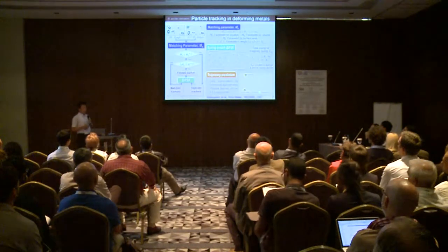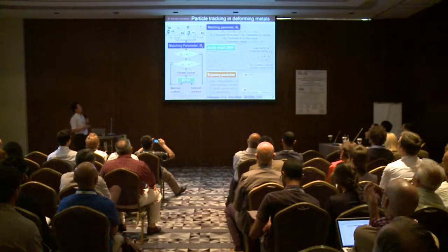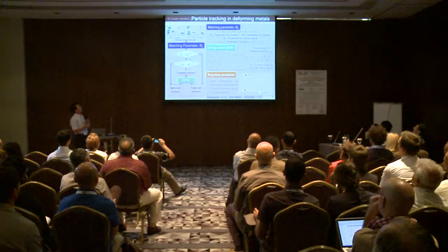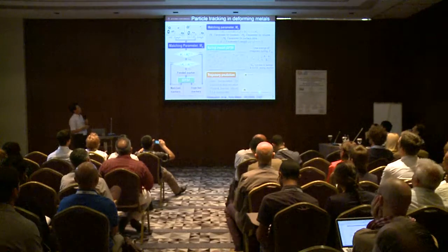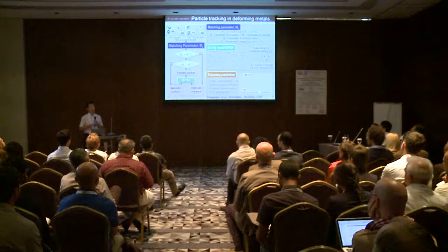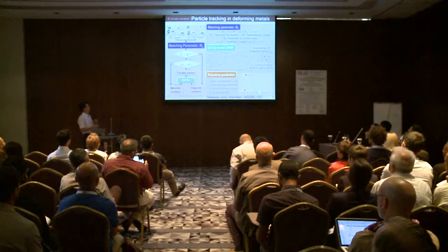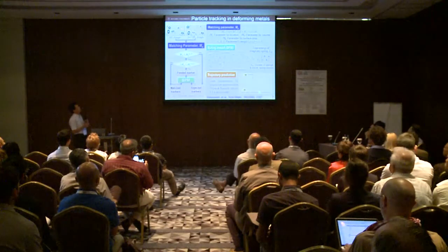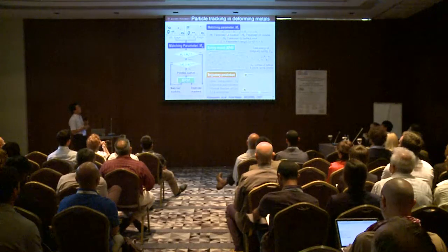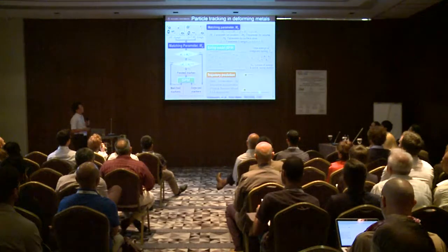So we would like to analyze the mechanisms of this hydrogen embrittlement behavior by tracking particles. We have a series of tomographic images, roughly 10 to 15. Then we can observe roughly 50 to 100,000 particles in the gauge section of a single specimen. Then we can track the physical displacement of all the particles by utilizing those morphological parameters. And we sometimes apply local pattern matching and trajectory prediction techniques.